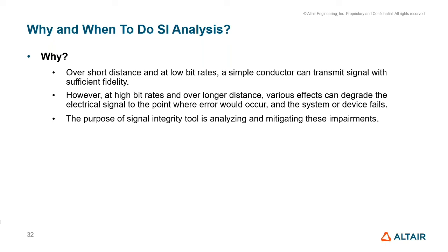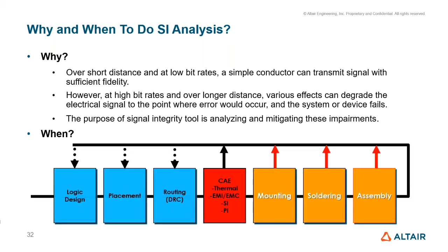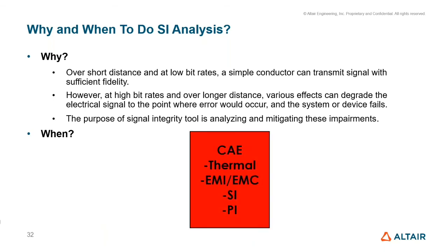Well, this takes us to the second question. When do we do DFE? When do we do signal integrity? Signal integrity, along with other solvers, is conducted after routing and success with DRC checks, and before manufacturing the board. So as you can see, this is where we do the signal integrity along with other solvers.